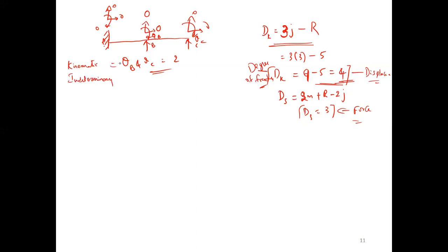So when you get MCQ questions, you have to verify both things. Sometimes you get 4 and 4 is there in the answers too. But what has he asked? Has he asked for degree of freedom or kinematic indeterminacy? You have to check. If he asks for kinematic indeterminacy, you have to do it like this only. I taught you displacement: due to fixity, because of all 3 reactions, it is 0 0 0 0. So in the SD method and MD method, this is how we do it. We don't use equations anywhere, because this is the displacement method. But if we are asked in a question for the degree of freedom, then you must use the equation only.